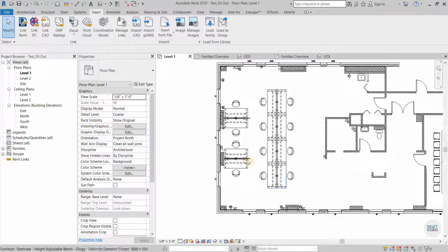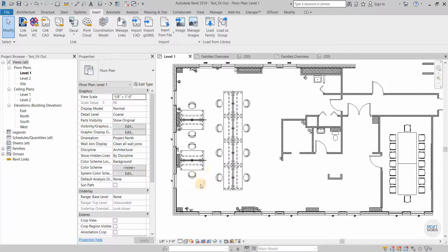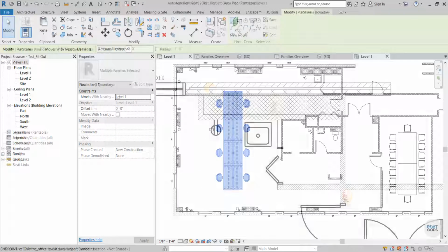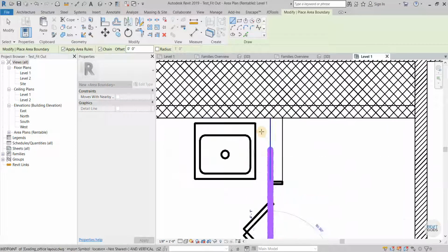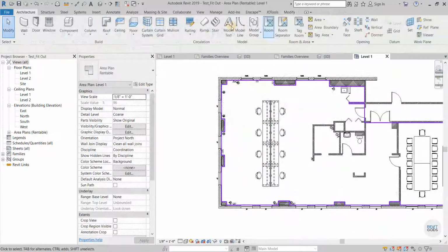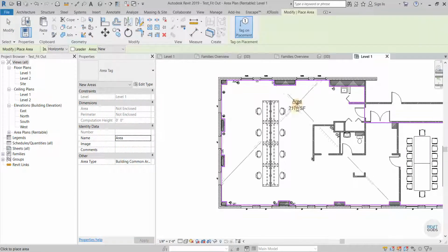This is pretty awesome. For the interior design profession, I think a lot of these things can potentially be a game changer. One of the things that I love is that I can actually do my BOMA plans here and get square footages right inside the program. Once I draw an outline, I can use the area tool to get the total square footage of a space, whatever is rentable, or I can do gross square footage, whatever I decide.